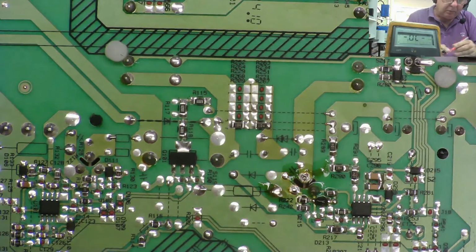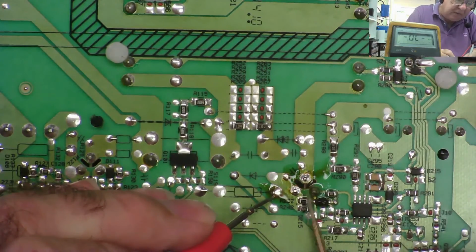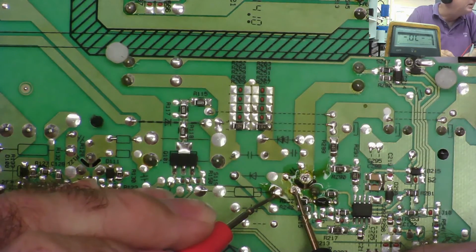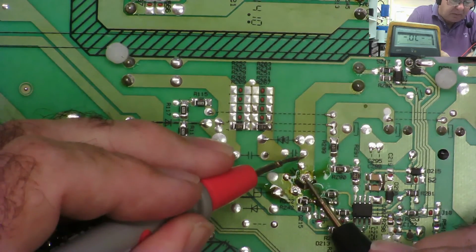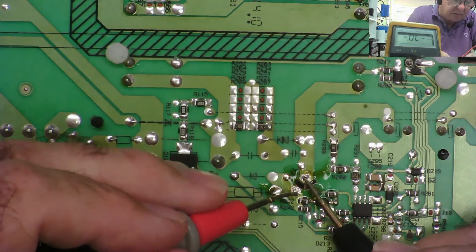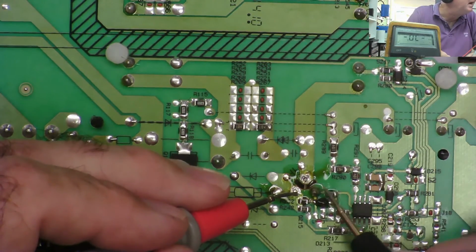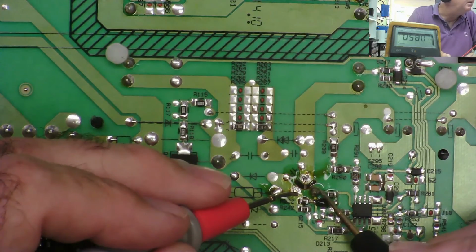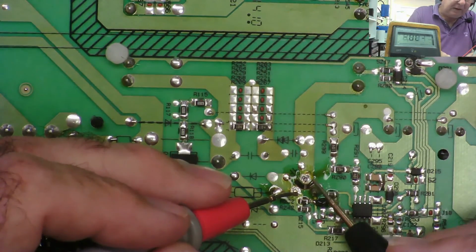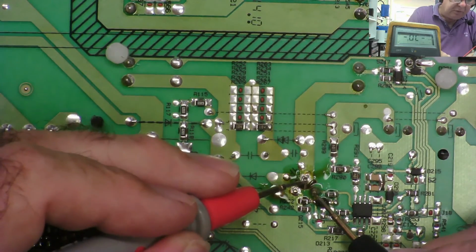So now, on this transistor, from this pad should go to this pin. It's not connected anymore, yeah? And the same from this pad, not connected. And we can now test, yeah, between there and there. It doesn't matter this one's soldered, because this one isn't soldered. So now we will only see a diode junction there, and you shouldn't see anything between these two.